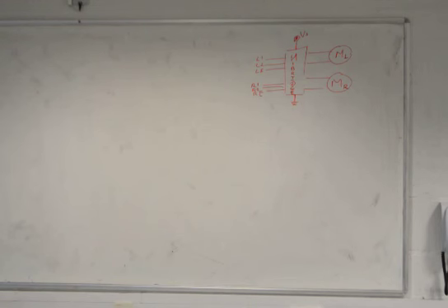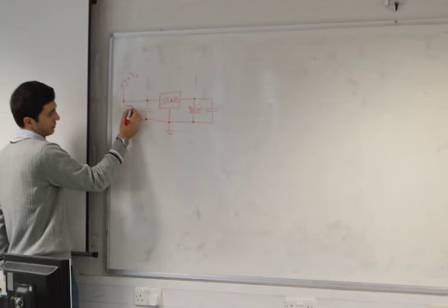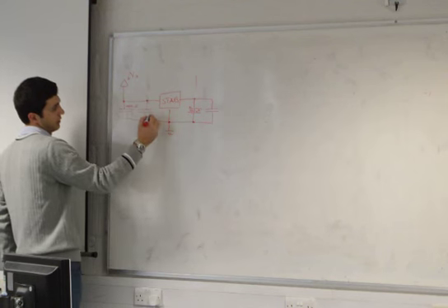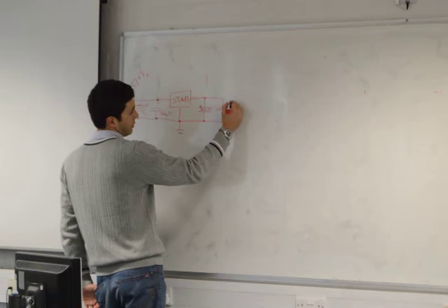In here we will have our plus. Let's say we supply the circuit board with 12 volts, the voltage that we're going to use to control the motor. So let's write VS, voltage supply. Let's say 1000 microfarads, and the same 100 here.